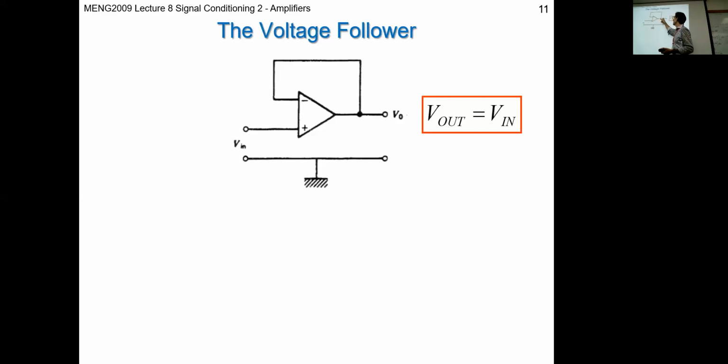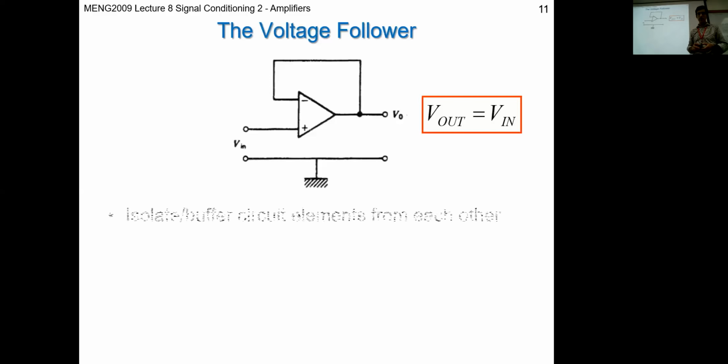And on the output, the property is very low impedance. That then allows us to have a higher level of current flow on the output side. We haven't got any gain, the same value of voltage out as you get in, but you're now using the characteristics of the op amp to help you develop an effective measurement system.